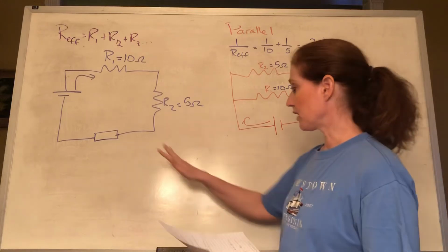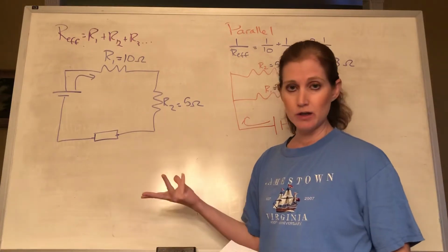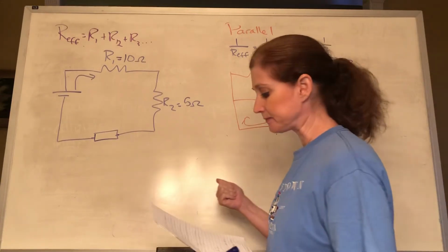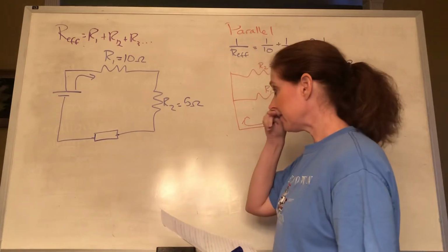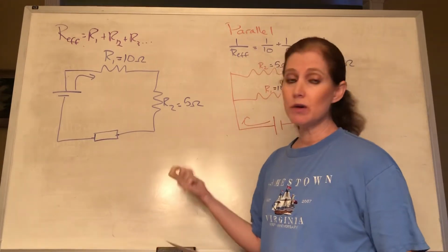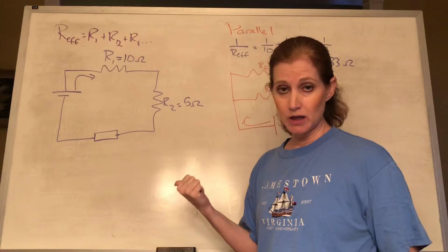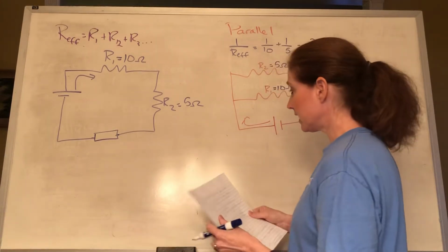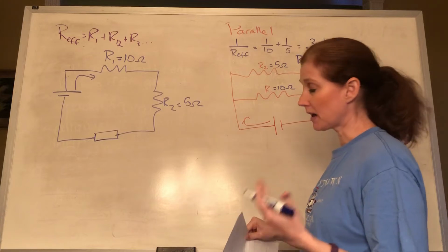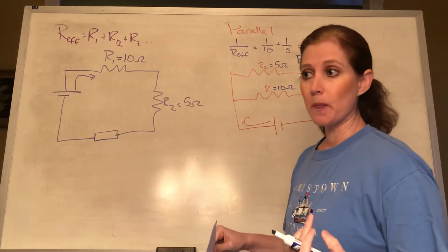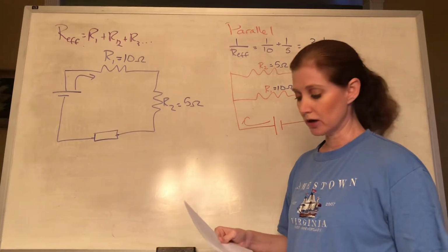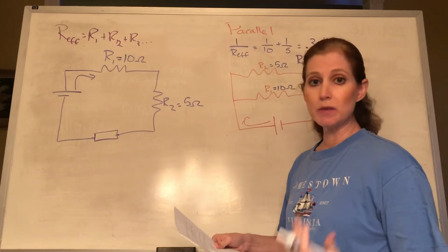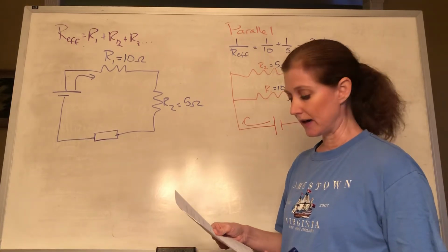In that case, like I said, we got blowing the fuse, and we'll say the circuit breaker's been tripped. Okay. All right. So if your fuses keep blowing or your circuit breaker keeps tripping, you've got a problem that you've got to fix. And sometimes it's that the appliance needs to be repaired because it's drawing too much current, or there's too many things plugged into an outlet.